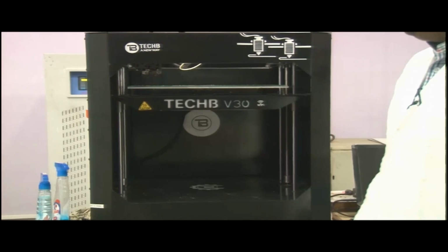About FDM and SLA: FDM machines produce products with precision, but the precision level in SLA is higher. Higher resolution objects are more possible to produce in SLA because resin is there. The resolution is primarily determined by the optical spot size either of the laser or the projector, and that is really small in SLA. In FDM, it is the printer. The printer resolution is a factor of the nozzle size and the precision of the extruder movements. That extruder we will discuss in this demonstration as well.